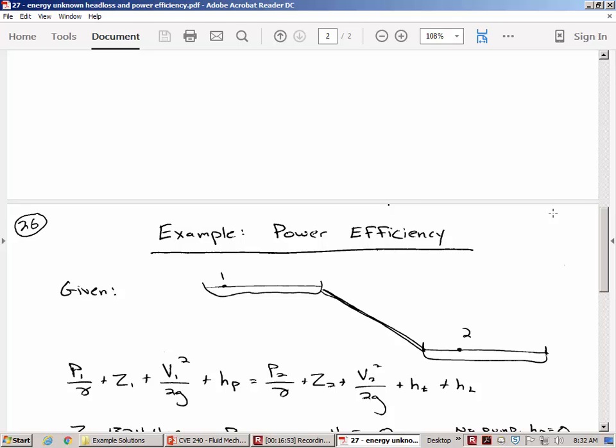Now there may be like a wind blowing on the surface, and so there may be ripples, or if the water level is falling a little bit, it may have some downward velocity. But the thing is the velocity is going to be so small that if you put in some number like 1 centimeter per second into the velocity head term, even if you did put in the actual velocity, that velocity head term is going to be negligible.